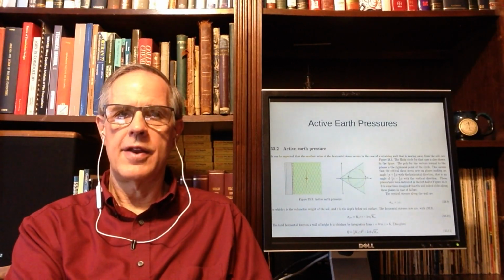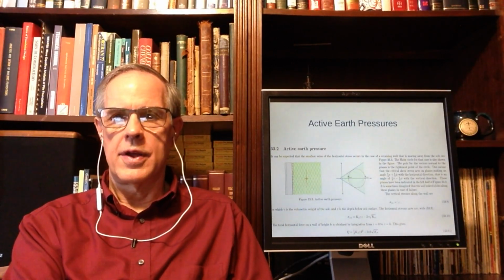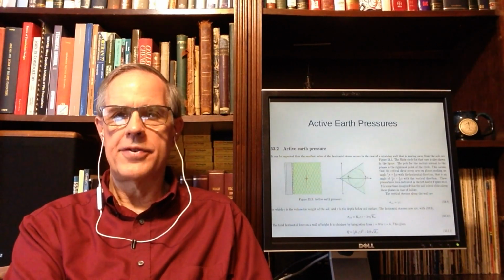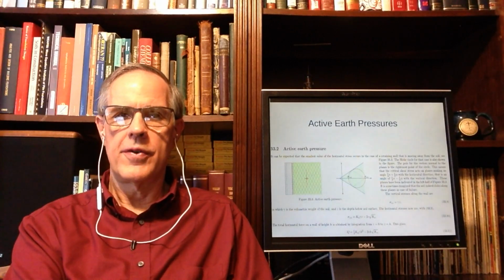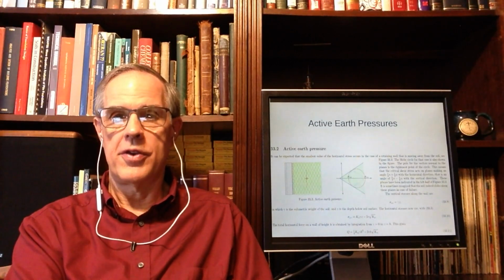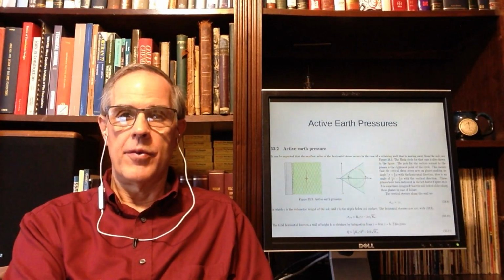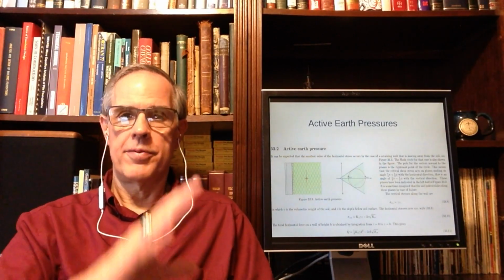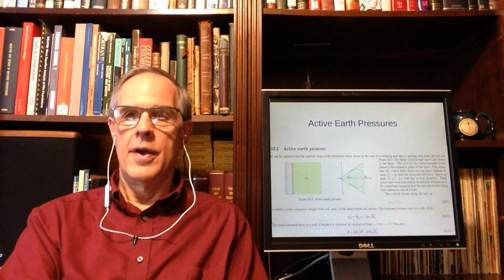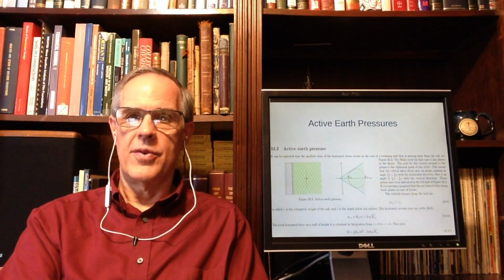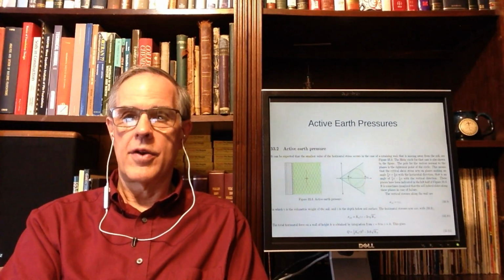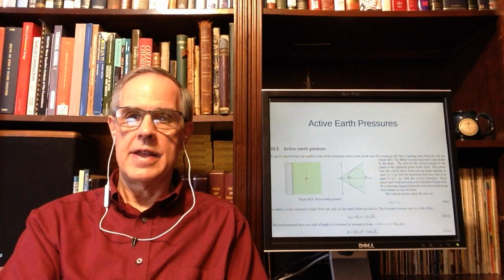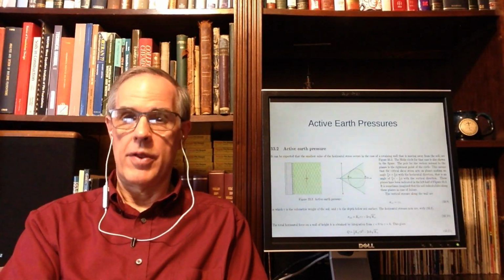I discussed that extensively in soil mechanics, where you have regions in the wall where you've got no pressure at all. The soil holds itself up without the help of the wall, at least for a little while, and that sort of thing. You've got the tension zone or zero pressure zone or whatever you want to call it. And cohesion also affects the action of the wall below that as well.